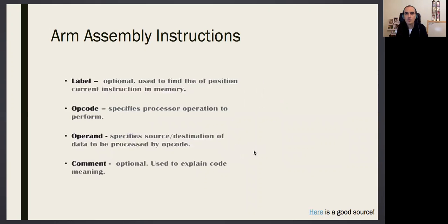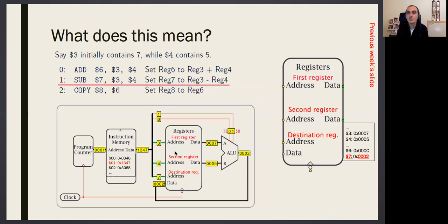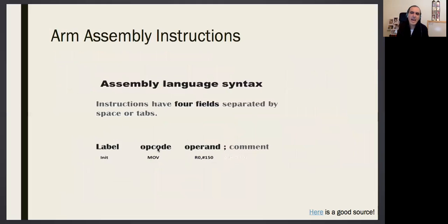Usually the ALU will do its operations on the registers, guys, most of the time. And we'll see that. So you'll write something here, add or multiply, register 1, 0, for example, move, which simply does this operation. You move this decimal value, 150, because I don't have 0x here, and it writes this decimal value over R0. Simple. And this was ARM assembly, guys.